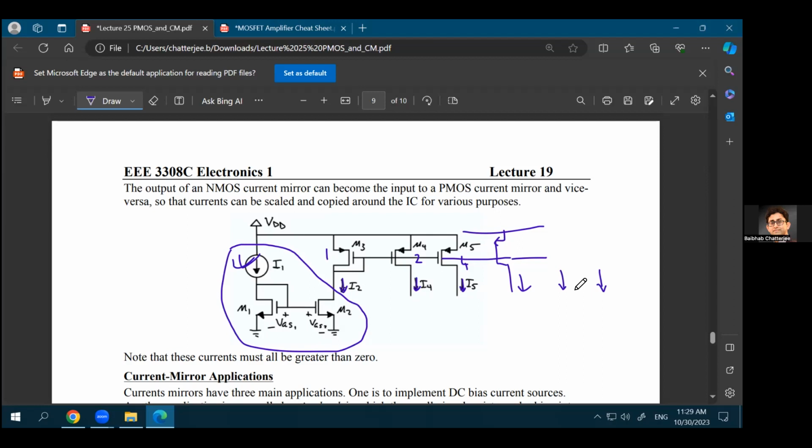And you can provide these current sources to multiple components of your system. So you eventually have only one single current source externally, but internally you can feed that current to multiple different components, so that you can bias all the different components separately just from one single external source. Question?